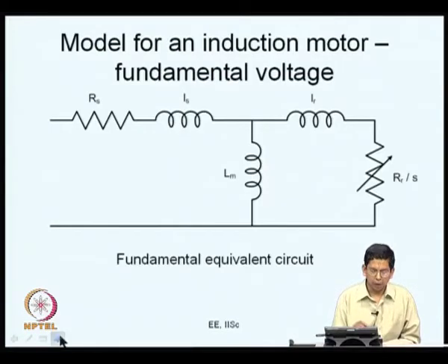Up to this point we have seen Fourier series and waveform symmetries and how you calculate the various harmonic components. So, we now have the ability, given a PWM waveform, which is actually a periodic waveform, to calculate the fundamental and the various harmonic voltages. Now, when harmonic voltages are fed to certain loads which we normally come across, how the harmonic currents would be is what we are looking at now. So, this is the next thing.